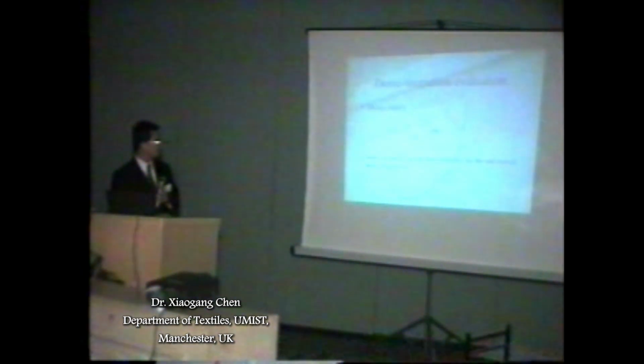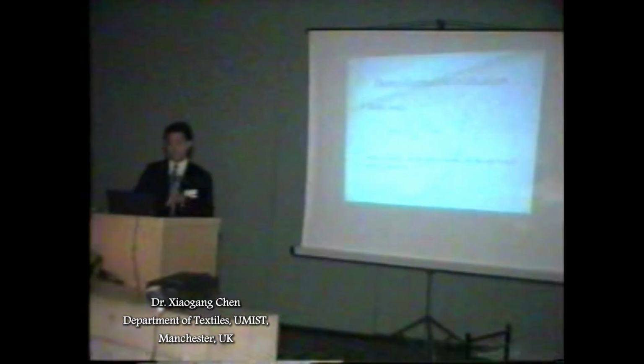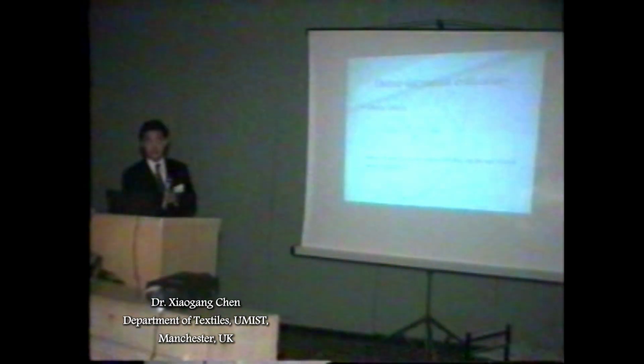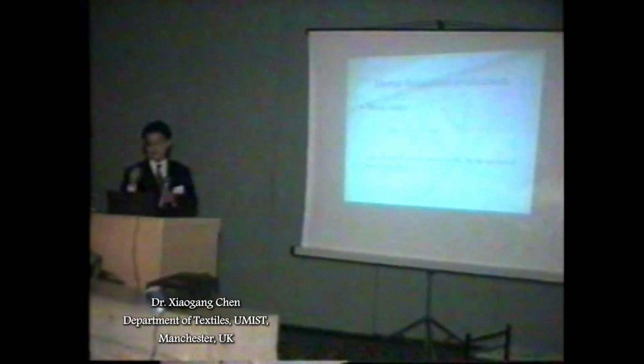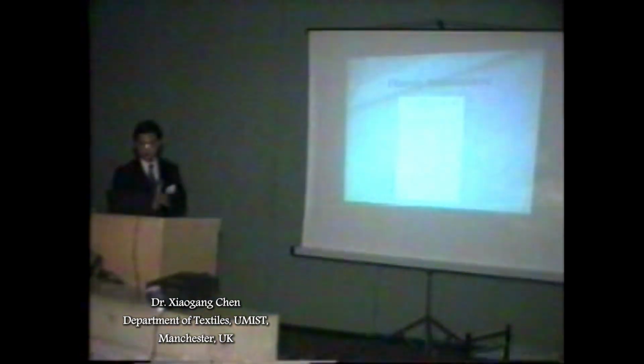DI is the fabric density for the flat areas, and DM is the fabric density for the domed areas. The dome index is DI minus DM over DI, times 100. We used this index as one of the measures to evaluate the formability of domes.